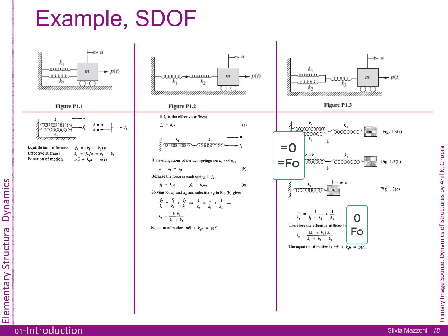When you've got springs in parallel, do the two springs have the same force, or do they have the same deformation? That's the question you've got to ask yourself. When they're in parallel, you can see here, you've got this little block, and this guy's going to move to the right, and it's going to take those two springs along with it. So when the springs are in parallel, they have the same deformation and different forces. One spring is going to be easier than the other to pull if they have different spring coefficients.